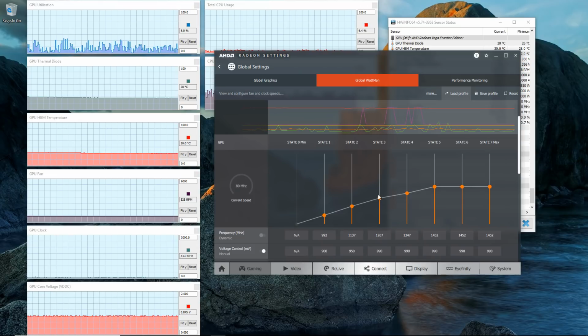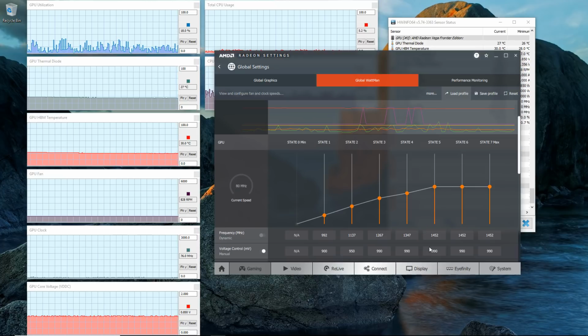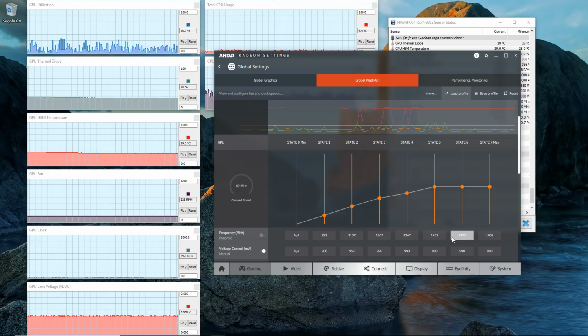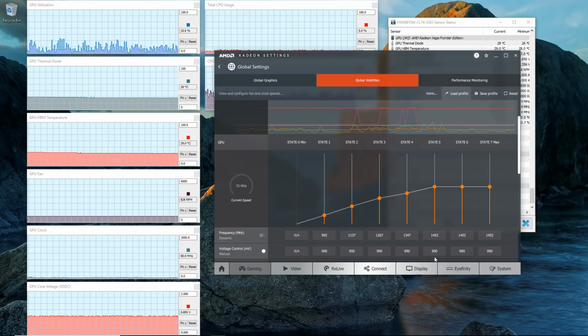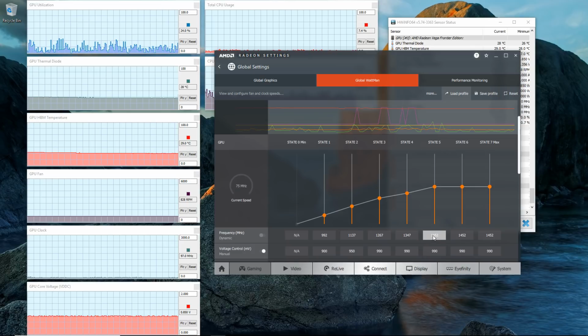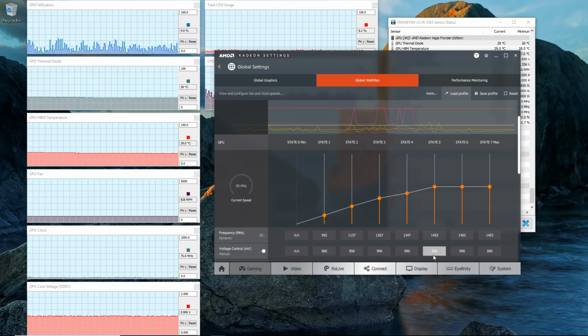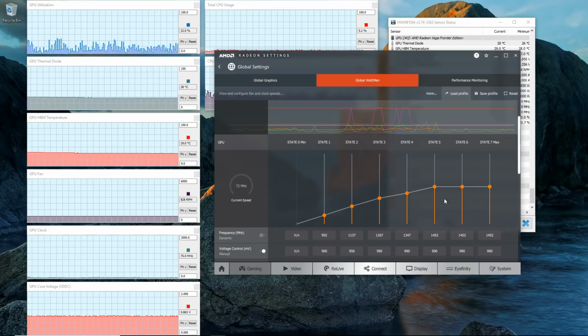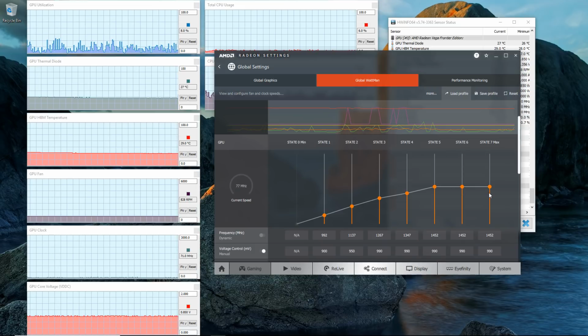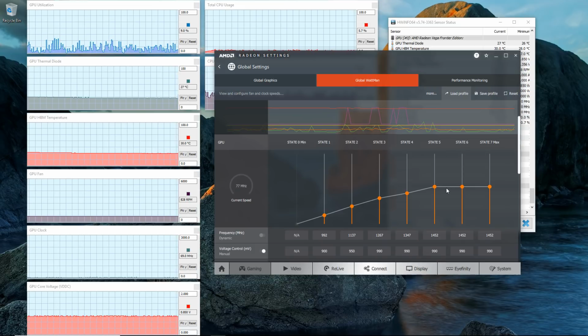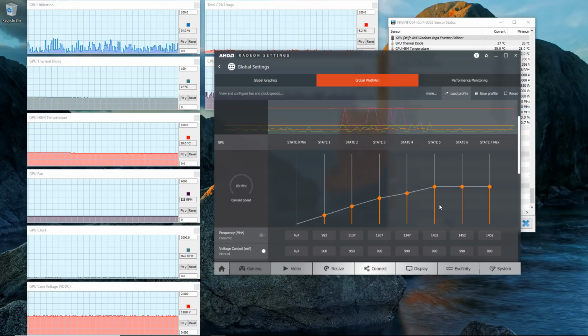That gives me better thermals up to this range, and I know that everything from here back is stable. So I've effectively locked in my state 5 frequency. I know that this setting is stable. It doesn't matter if it hits this setting in state 5, state 6, or state 7, the card is in the same condition, and therefore I know that it's stable.